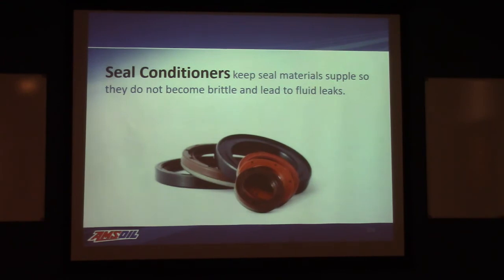There are additives, or other materials that can be added to the oil to change the way it reacts with these materials. One of the things that many people do is use synthetics. There are certain synthetics, PAOs for example, which tend to be very neutral when it comes to these type materials. They don't cause them to swell, they don't cause them to harden, they don't do anything.